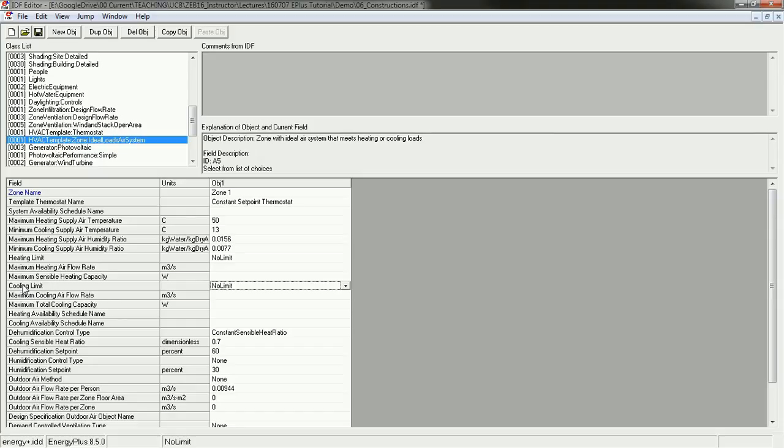It's also a 100% efficient system, which is equivalent, say, to electric heating being 100% efficient. The exact amount of power that you put in is the amount of heating energy that you get out. Actually, 100% efficiency sounds like an efficient system, but it's really not, because if you look at electric systems like heat pumps, they can be 250 to 500% efficient relative to the energy that you put in.